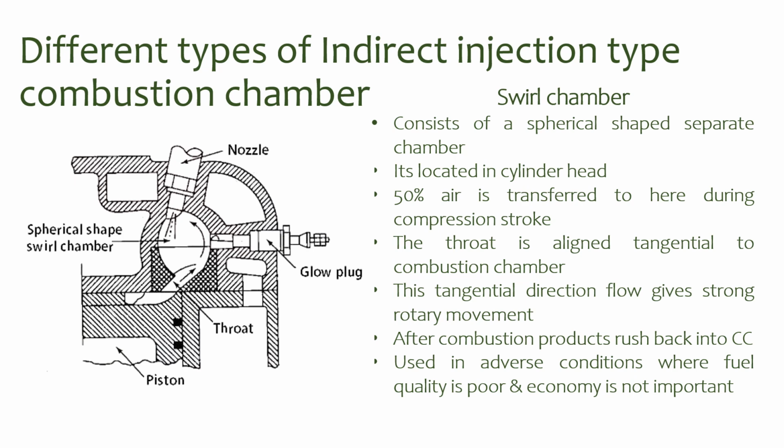The throat is aligned tangential to the combustion chamber. The tangential direction flow gives strong rotary movement. After combustion process, the combustion products rush back to the combustion chamber. This type of combustion chambers are used in adverse conditions where fuel quality is poor and economy is not important.